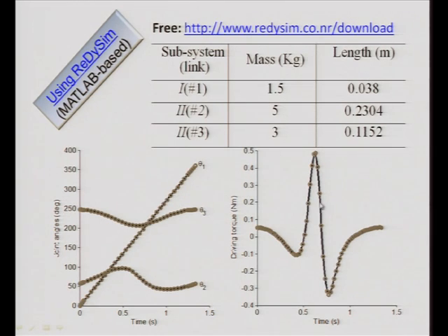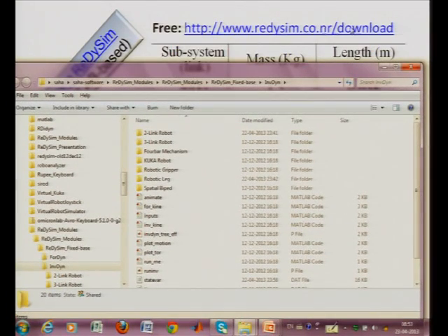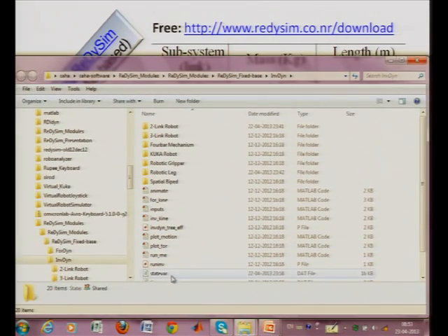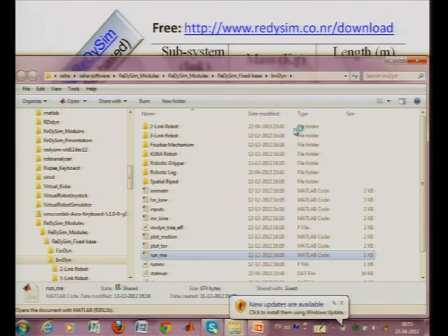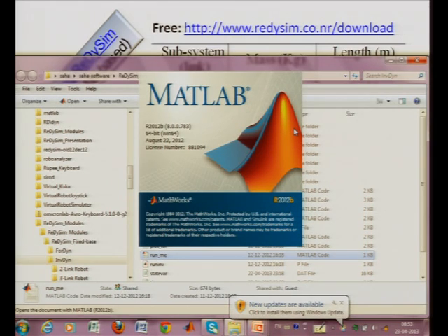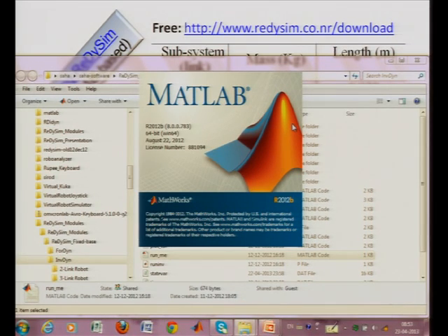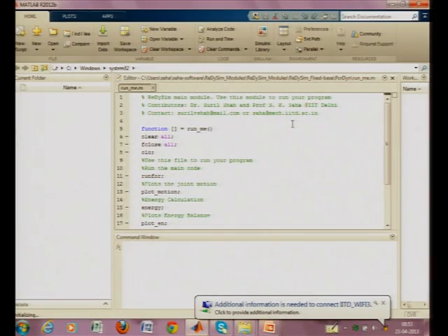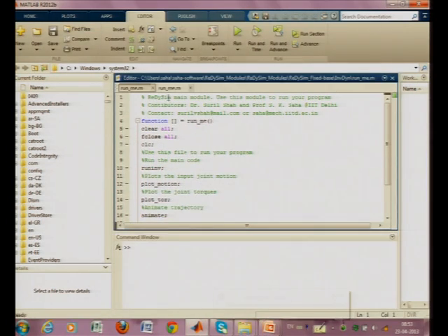Okay, so, here I have the results for the 4 bar linkage, but I will show you this one using one MATLAB based algorithm which is available through the net also. So, this is the website as you can see it, and then I will run this MATLAB program. This MATLAB program is actually meant for the tree type system or open loop system, and then a small module has been added to take care of the constraints, the J transpose lambda calculation, and after that it is using the same stuff.